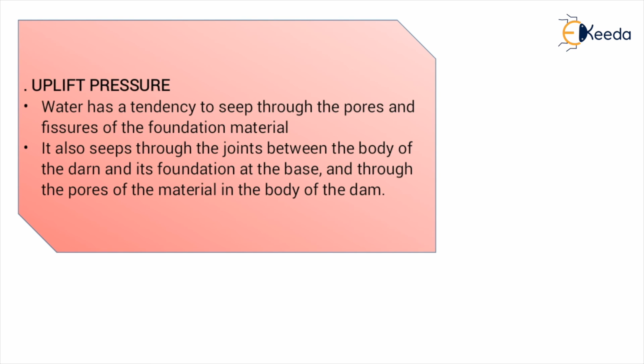So there are design criteria for this uplift pressure also. According to this, no reduction in uplift is assumed at the downstream toe of spillways on account of reduced water surface elevation that may be expected immediately downstream of the structure. It is assumed that uplift pressures are not affected by earthquake.